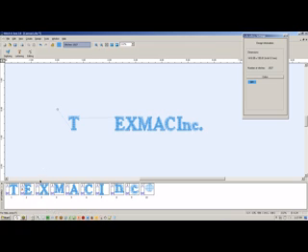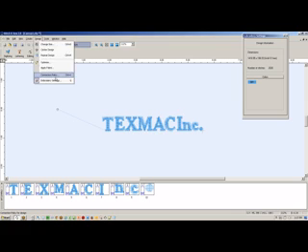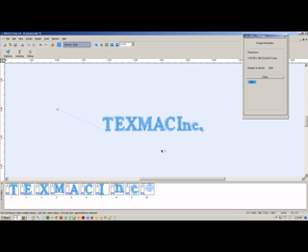Now we don't want to do that. We'd like it to trim a little sooner than that, so you can always play with that. You can go to Tools, and then to Design, set your connection policy to something more meaningful, like anything bigger than 2 millimeters, which would be 20 in this dialog box, or 20/10 of a millimeter. And now if I start moving stuff away that's not too far, if I generated the text fresh, then you'd see that trim.